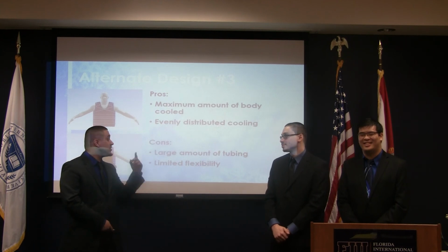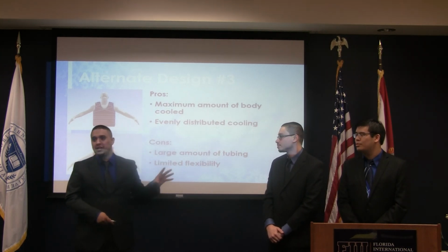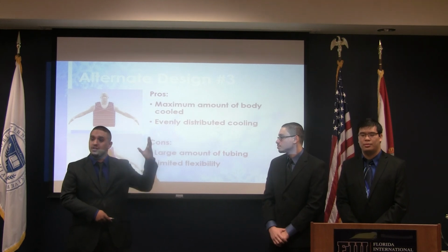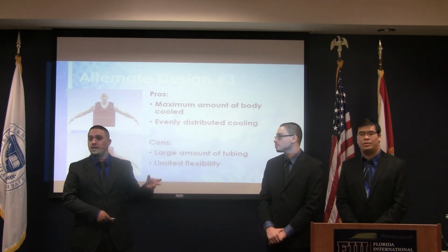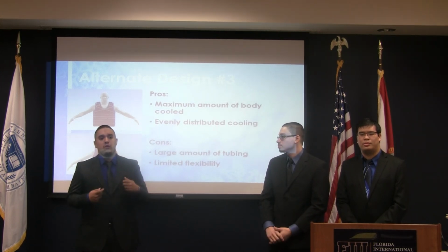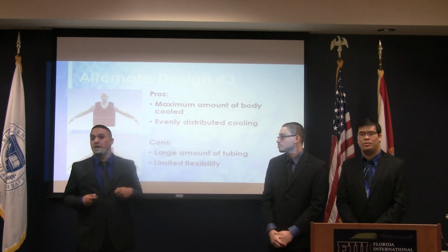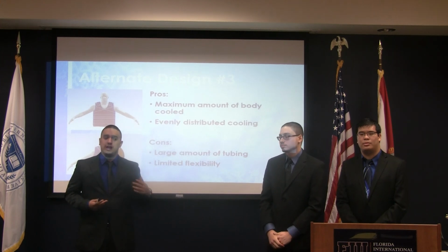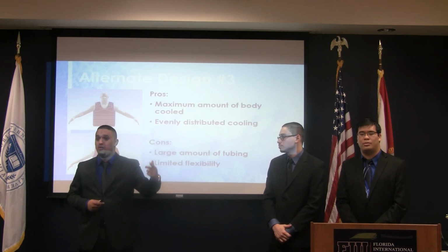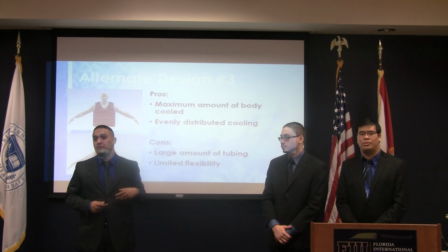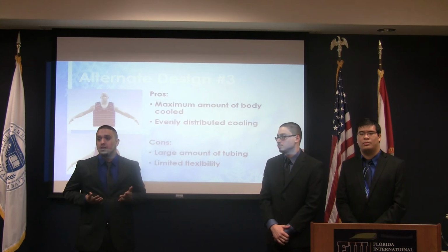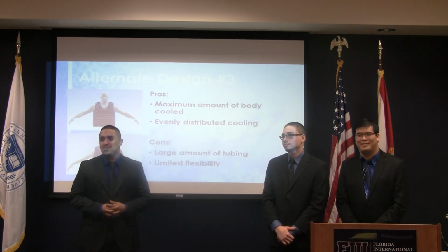In regards to condensation, there are two reasons why condensation is our biggest enemy. Number one, too much freezing of the Peltier plate could drastically reduce its efficiency and also completely destroy it over time. And number two, to your point, we do not want to make a system in which people wear it and all of a sudden they're getting wet due to the condensation. So the idea is to not lower the water temperature so low that the moisture in the ambient air builds up on top of that tubing. That way, you wear it, it's dry all the time, and you never have to worry about wetting yourself. Because it would be highly uncomfortable.